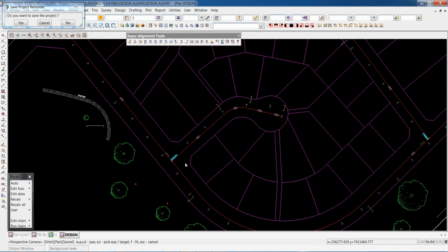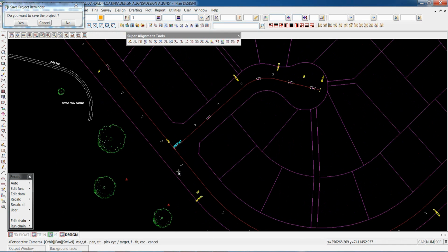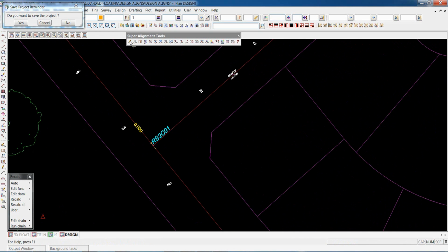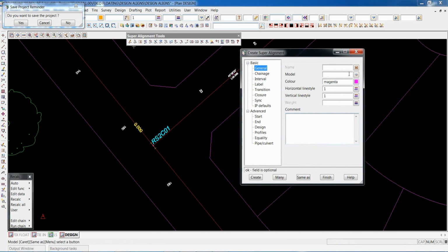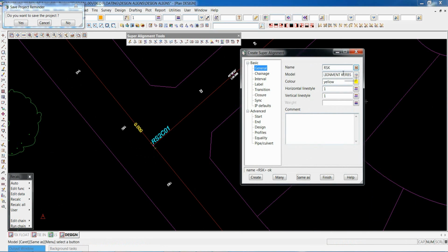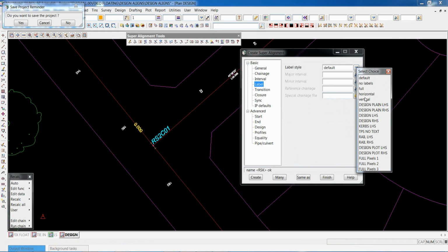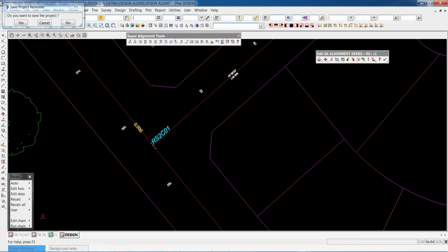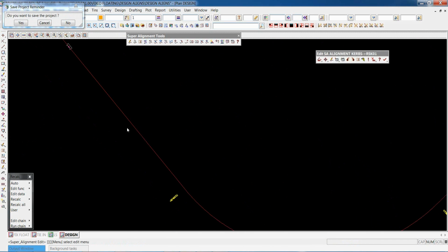So now look back at our urban type development. If we looked at the fixed and floating, or the free one we did for the main road, we would also adopt that for our curb return. So in that case here we're going to our curb return geometry. Again, we're going to pick up our curb returns. Look at our labeling. Create.